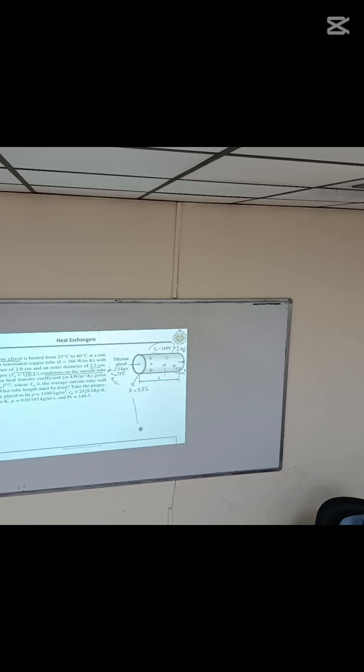So now we can expect the temperature profile. This will be TG, 110 degrees Celsius, and here is the cold fluid, TCI to TCO.